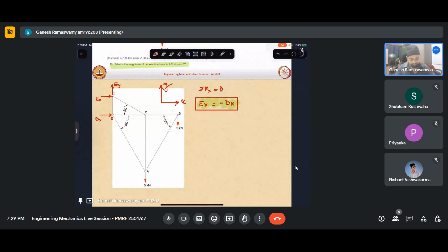But even by inference, we can see that this force is pointed downwards. So essentially, these applied forces will try to rotate the truss like that. But we know that the reactions, the pin and the roller, are keeping it in equilibrium. So if the applied moment is like that, then the reaction moment would have to be anti-clockwise.